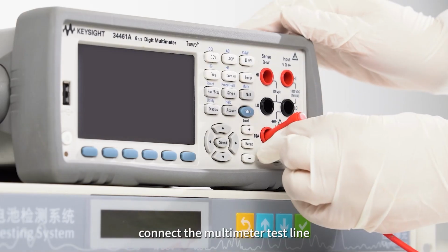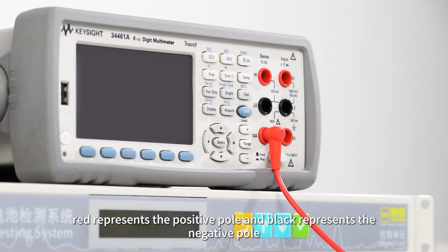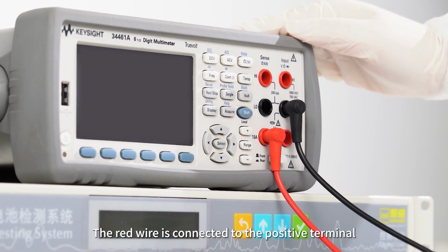Next, connect the multimeter test line. Red represents the positive pole and black represents the negative pole. The red wire is connected to the positive terminal. The black wire is connected to the negative terminal.